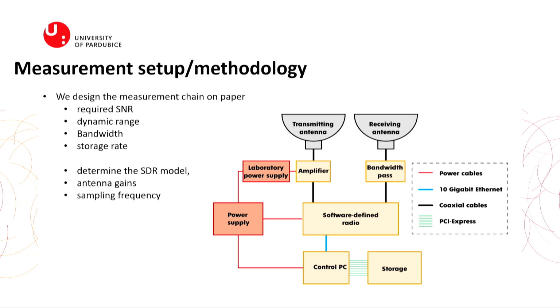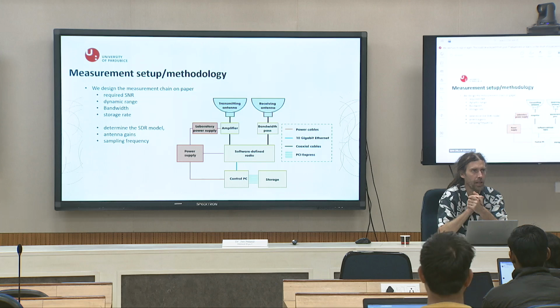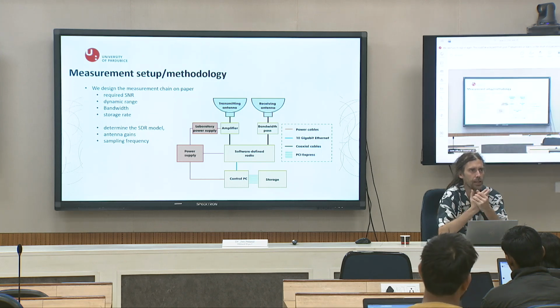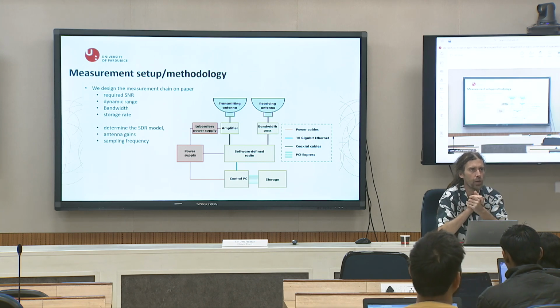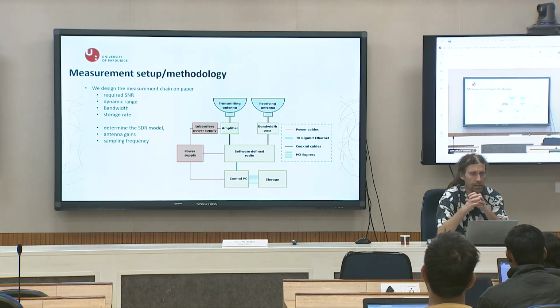So you also need to know the dynamic range of your signal, because if you are too close, the reflected signal could be so strong that it could destroy your SDR. In the other case, if you are far away, then you have the opposite problem: the reflected signal is too low. So the dynamic range you can expect is very important, and you can evaluate it in advance before the measurement.